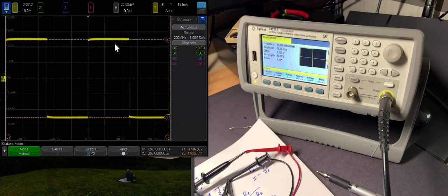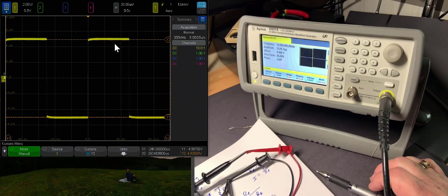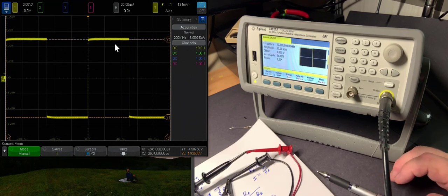So it's just a fine adjustment on the calibration of the probe. Not necessary. Again, there's a limit to the accuracy we can get with one of these scope probes. Now we've got the measurement with the probe corresponding to the measurement with the coax cable.